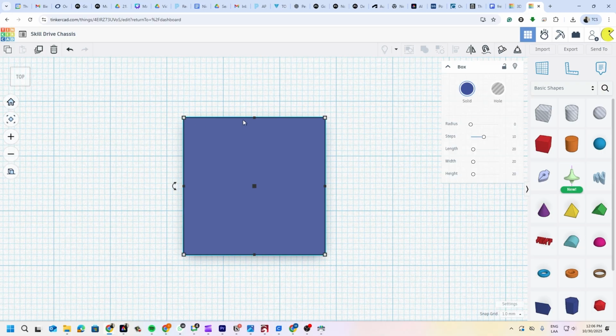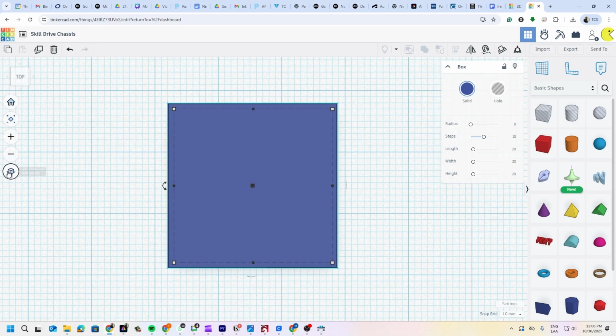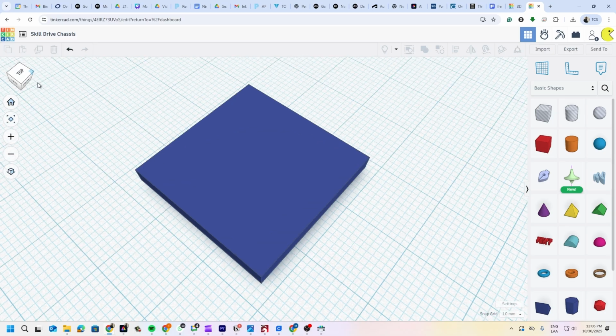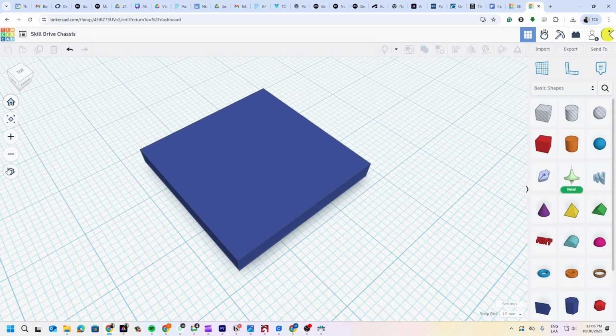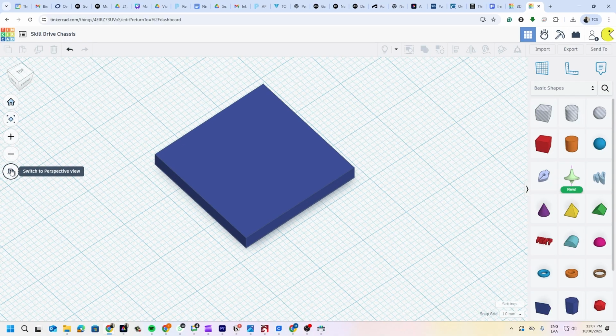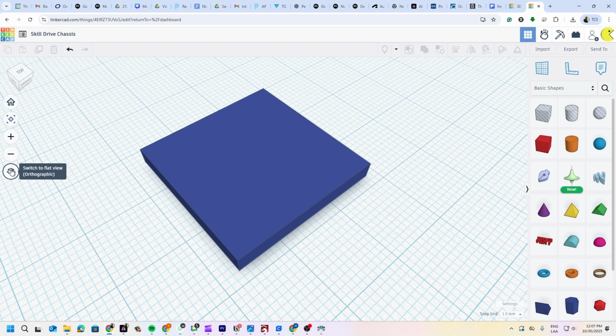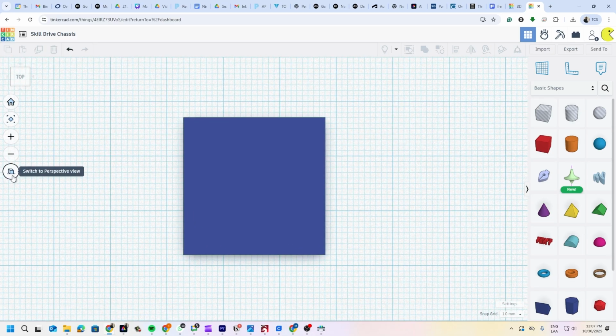And this is important because sometimes you want to take measurements or you want to locate or put some other objects here. Okay, it's not the same as having a perspective view. Okay, so this is very important. You see? It looks very different when we change from perspective to orthographic. So my advice is that you look at the orthographic view. Here we're in it, and you can see the icon right over here.